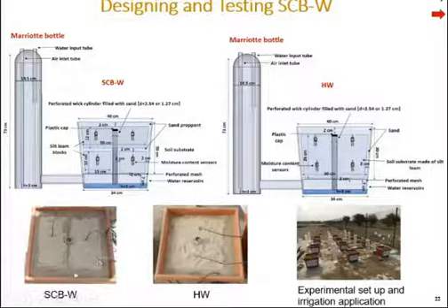This kind of structure creates a 3D capillary barrier that reduces evaporation losses from the soil and stores water in the soil, so you maintain more water content and don't lose the water very quickly due to evaporation. I compared this system with a control, which is just fine soil without the smart capillary barrier structure, and then ran the experiment.